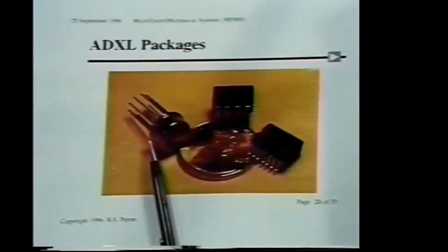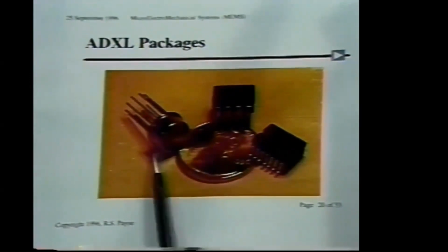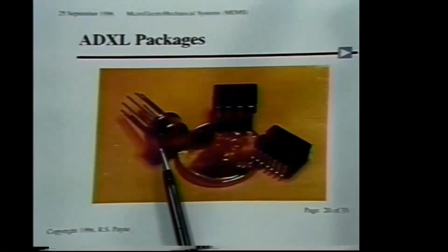The initial package, which was in a hermetic can, had the attribute that it's essentially welded. And so the properties of the device, which are established at room temperature in testing, were preserved very well through the process into the back end.